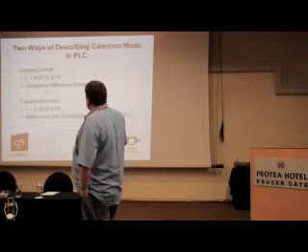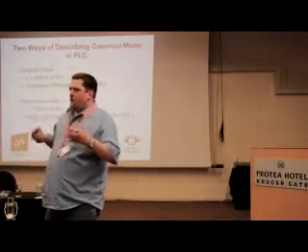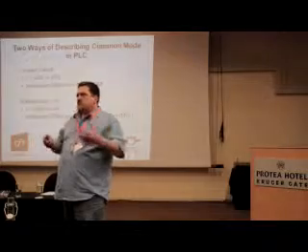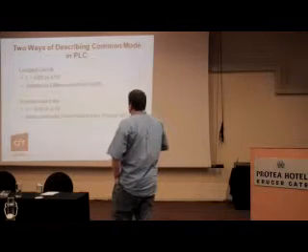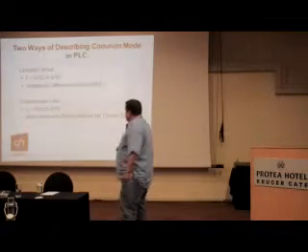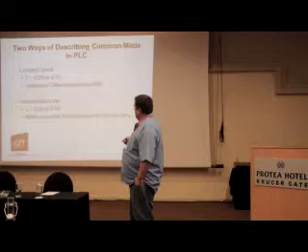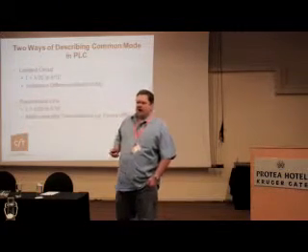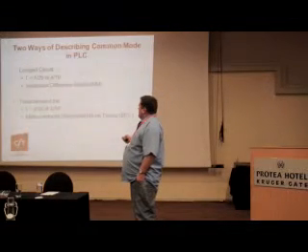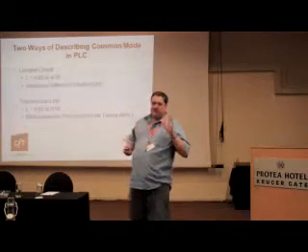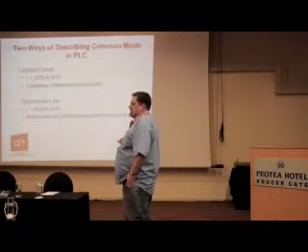So again, what we are trying to do is to understand how common mode is produced or coupled from differential mode. There are two ways of describing common mode in PLC. The one is lumped circuit theory, and there's a limit. I've heard the word bound. I don't know if it's a bound, but there's a region, and the region is lambda over 20 or lambda over 10, depending on who you talk to, where lambda is the wavelength of the frequency that you're working with.